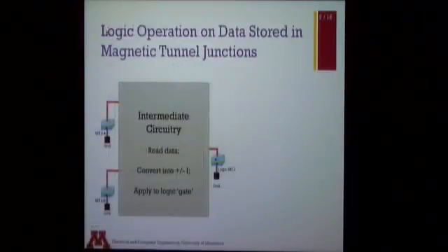So coming back to the sense amplifiers, the problem that we were working on for quite a little while was this. We have these devices that can store data. We have this device which can perform a logic operation. What does it really take to go from here to here? Now it takes a lot of intermediate circuitry. What is that intermediate circuitry doing? It's reading this data, converting it into the kind of input that this logic device needs, and then it's applying it to that input, and that's how we get our output.